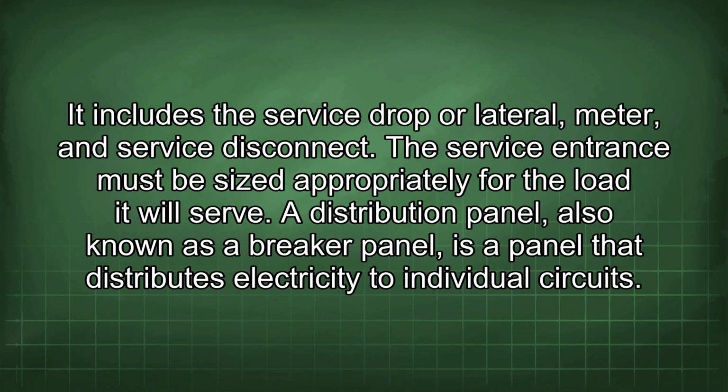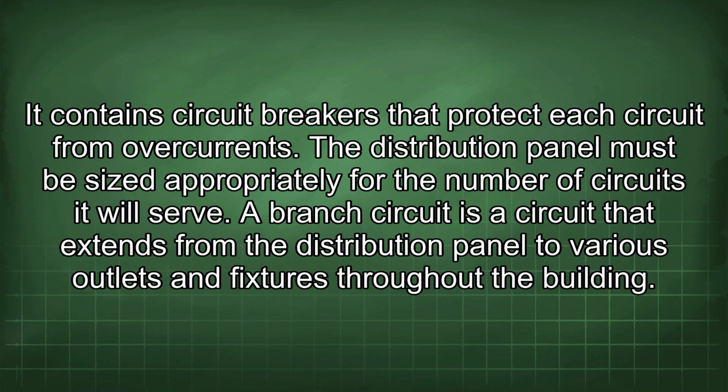A distribution panel, also known as a breaker panel, is a panel that distributes electricity to individual circuits. It contains circuit breakers that protect each circuit from overcurrents. The distribution panel must be sized appropriately for the number of circuits it will serve.